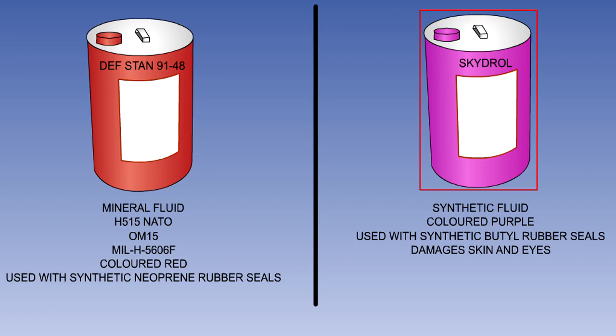In the event of a leak, it may spray out as a fine mist, and eye protection must be worn when investigating leaks. If any hydraulic fluid does come into contact with eyes, then they should be rinsed thoroughly with clean water. A medical assistant should be sought. It has a very high flash point of 170 degrees centigrade and is less prone to cavitation than mineral oil type fluid because of its high boiling point.